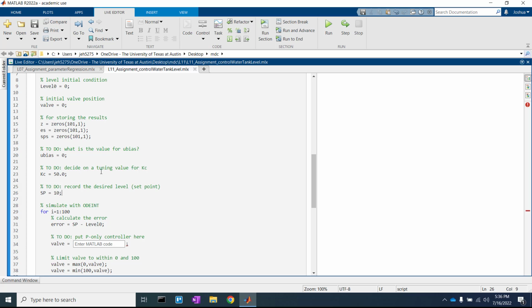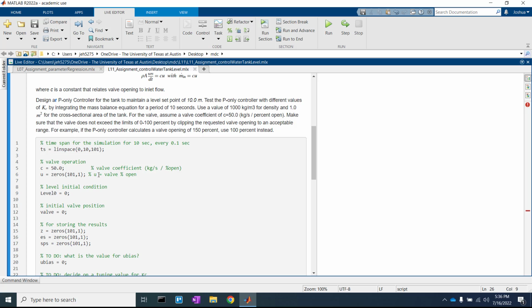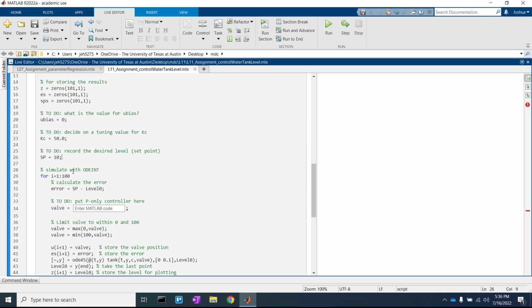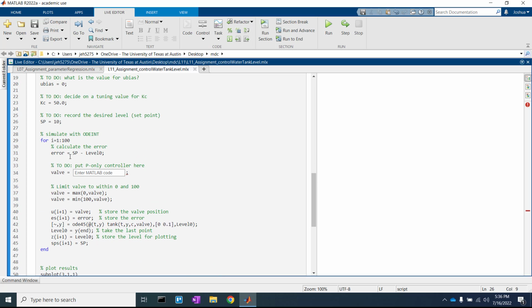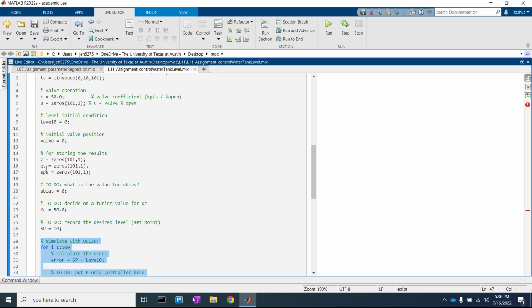We'll decide on a KC. KC is a tuning constant that relates error to the setting U. So let's look at our simulator with ODEint, and then maybe come back to some of these questions.